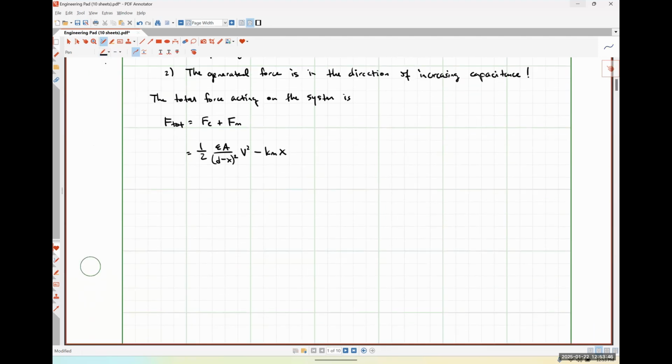All right, so I want us to figure out how to mathematically describe effectively this pull-in effect. So what we're going to do is treat this pull-in as an electrostatic spring force, okay? And so the total system stiffness can be analyzed.